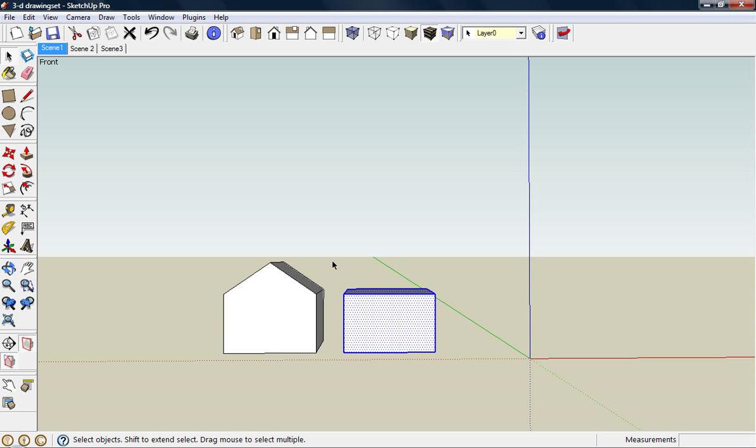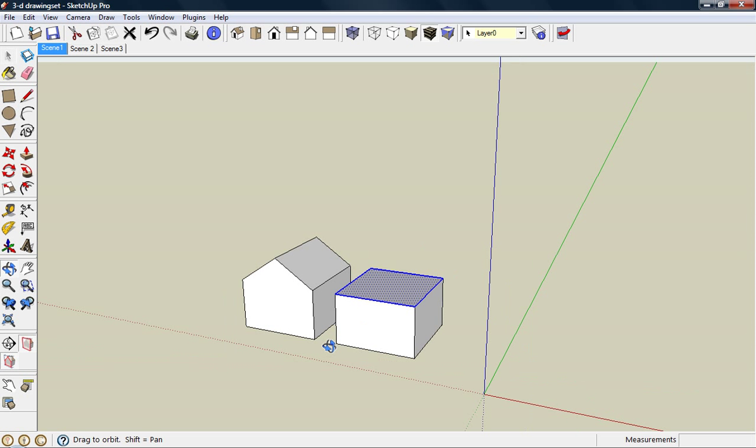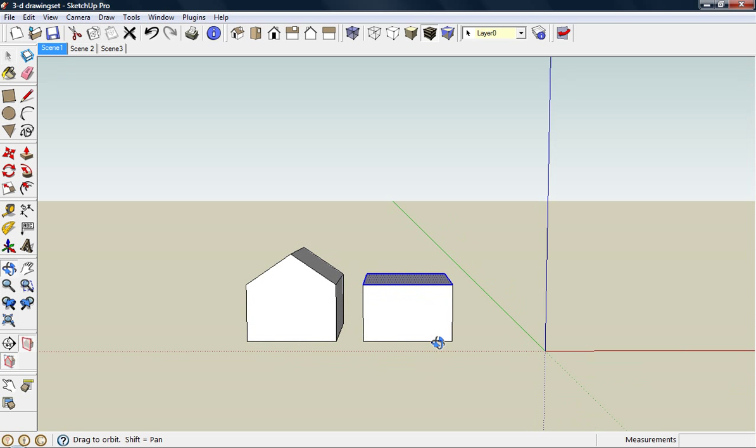Now the size and direction that you draw this box in will give you different results. So if I draw a box from left to right just on the upper portion here, when I let go, you'll notice that the only things selected were the edges and faces that were completely included inside that box.